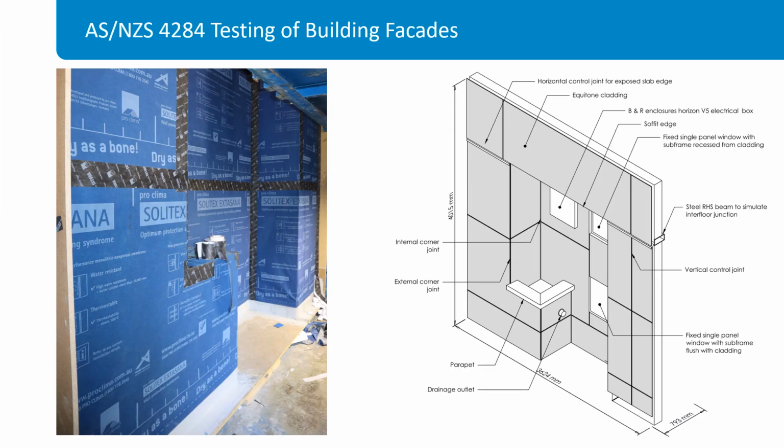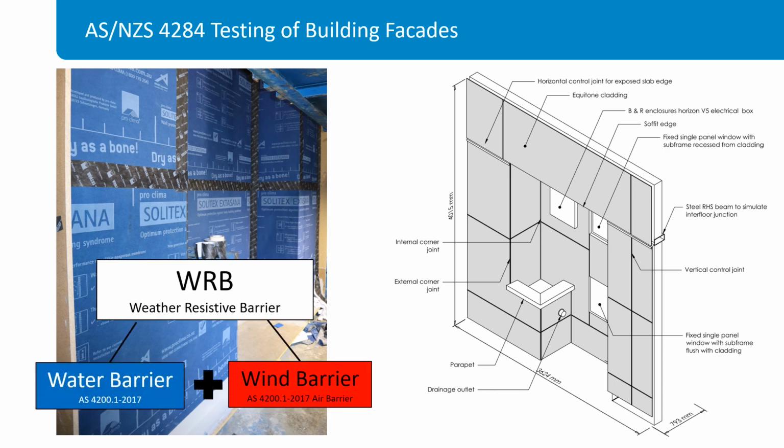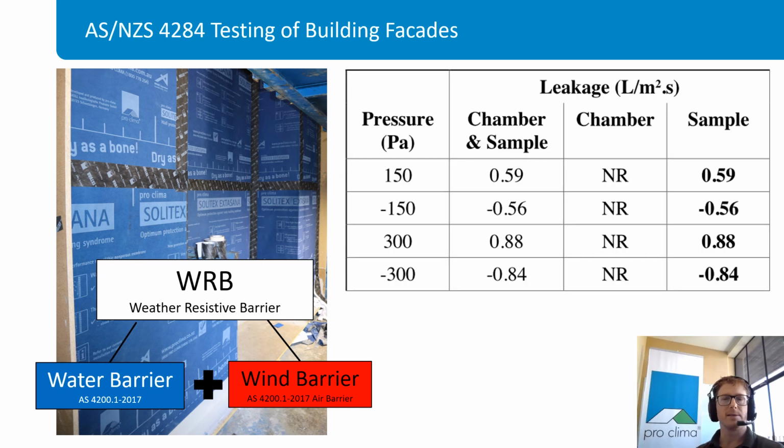So we're testing this system in the test rig. We've built it all up and we've got the components within the system all connected up. And it's all designed and it's all installed using water barrier materials, but also using air barrier materials to take the wind pressure, and all the connections are really well done. So we'd say that's going to be an airtight system, right? Yes, it is. It does deliver a degree of air tightness.